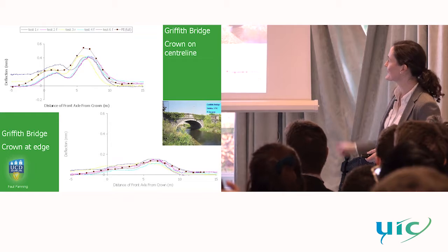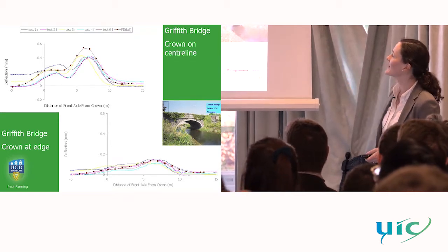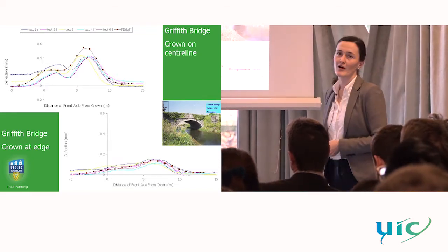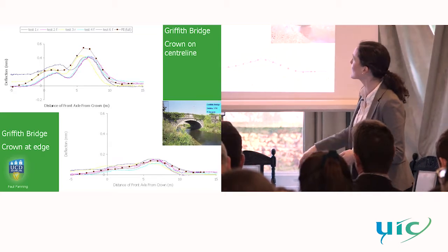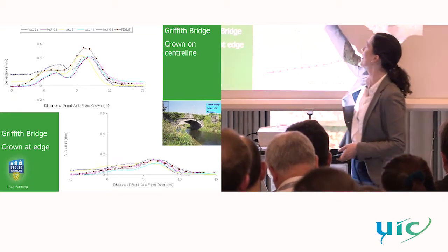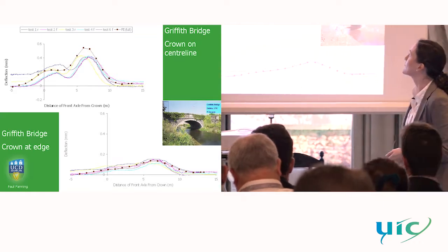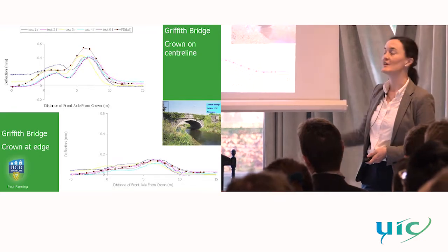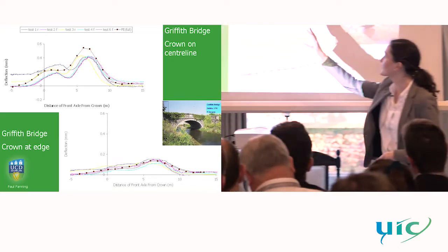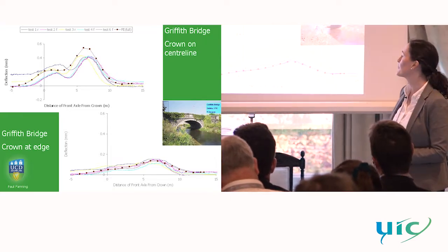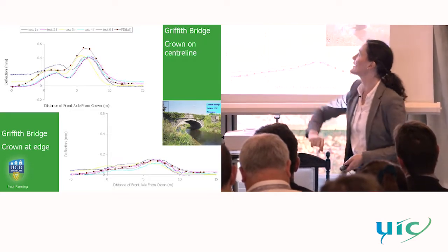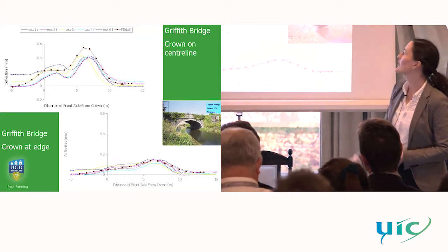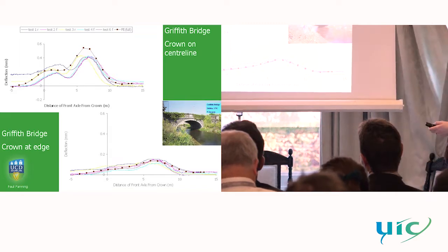Going back to the first bridge that I was showing, these are the deflection measurements from our service load tests, and the line with the markers on it is our finite element simulation. So really not too bad at all. These are at single locations, over multiple passes of the bridge. This one is looking at the crown of the bridge, and this one is looking at the crown, but out at one of the edges.